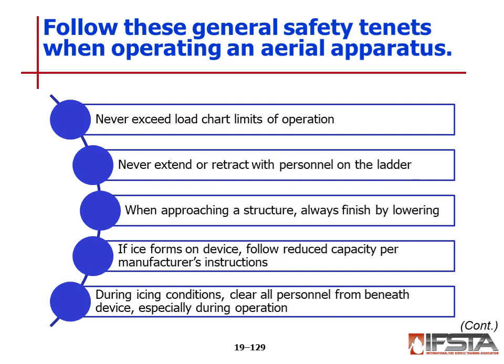Never exceed load chart limits of operation. Never extend or retract with personnel on the ladder. When approaching a structure, always finish by lowering. If ice forms on the device, follow reduced capacities per manufacturer's instructions. During icing conditions, clear all personnel from beneath the device, especially during operations.